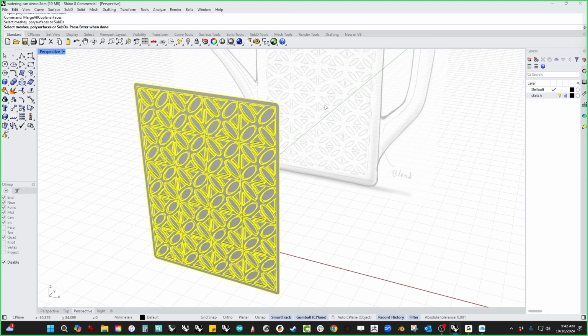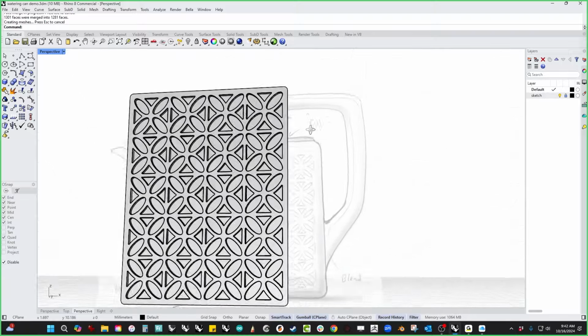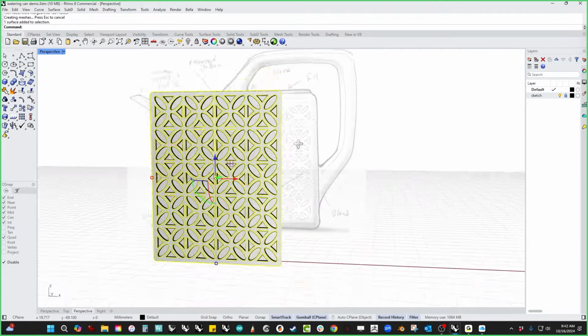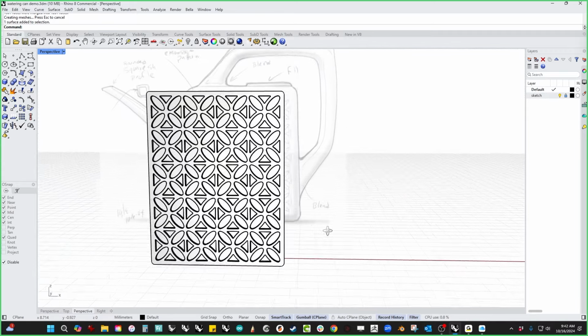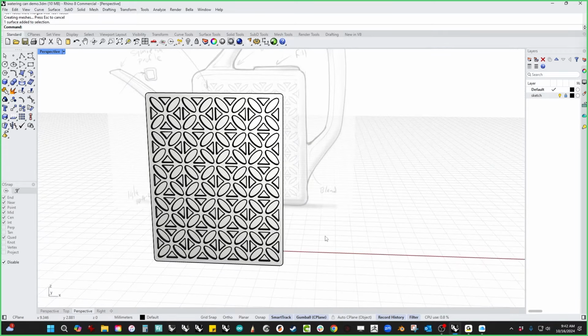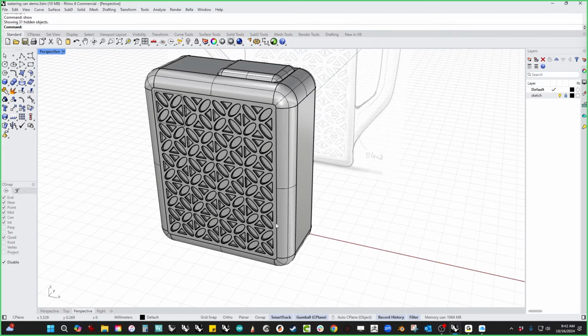And what we're going to do is pick this guy, and it's going to think, but it's going to go through and merge all of those individual faces into one trimmed face, keeping the fillets and all that kind of stuff, which makes this a much nicer thing, especially if you're going to do data transfer, if you're going to go to SolidWorks or UG or whatever you're going to do with it.